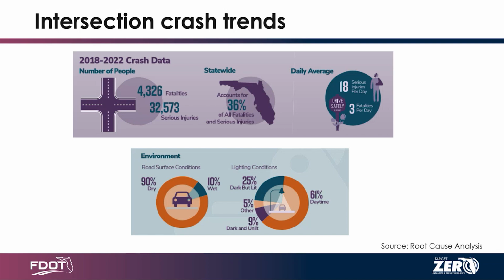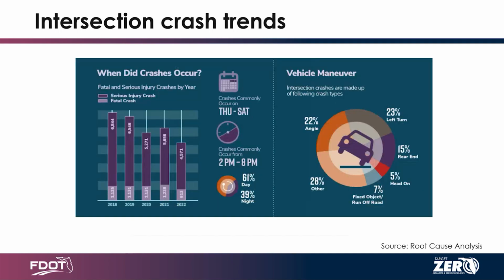And so I just wanted to reemphasize that these might be okay thresholds to use, but really it depends on the specific location and the characteristics. And also the number of crashes, because if you have two crashes, that really doesn't give you the big picture. So you want to make sure you have a large data set when you're thinking through these potential intersection countermeasures.